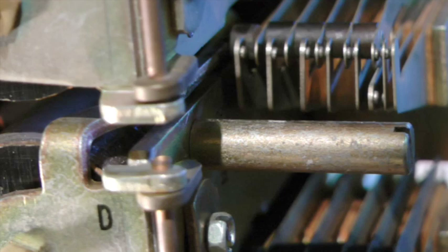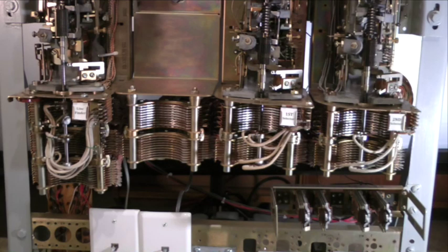First, if the start chain ground is removed because all active dial tone requests have been served. Or second, when the open chain multiple circuitry in the group and alarm relay circuit triggers the de-energizing of all D relay secondary windings in the line finder group. This only occurs when all 20 D relays in the line finder group are operated. And this is what the release of the switch train, including the line finder, looks like at normal speed.